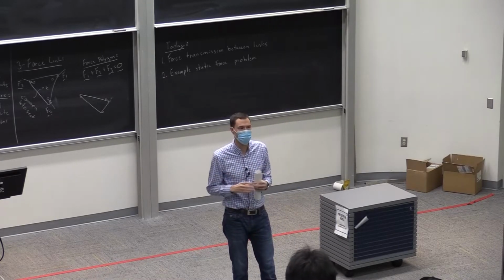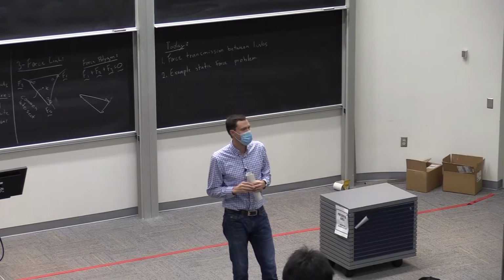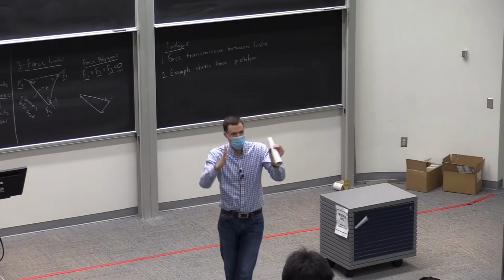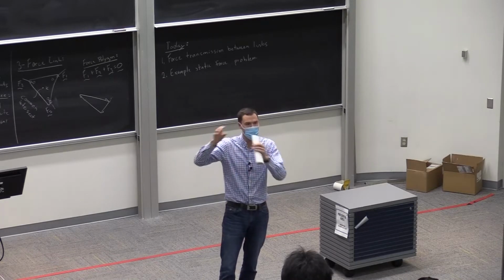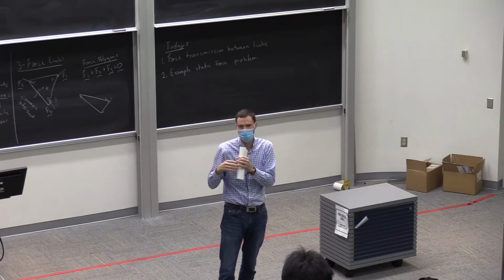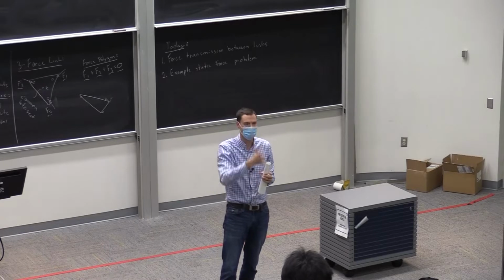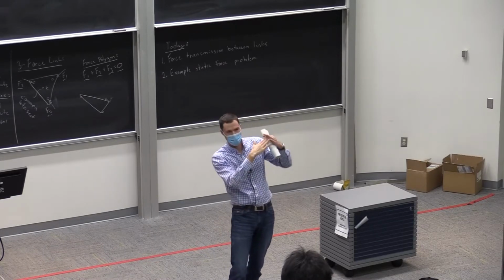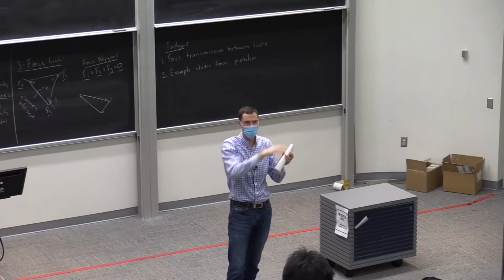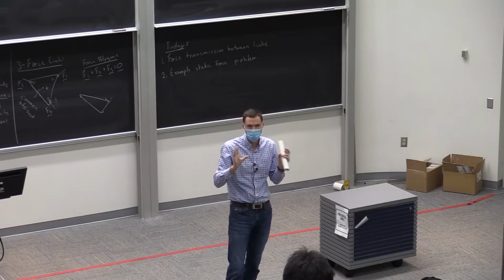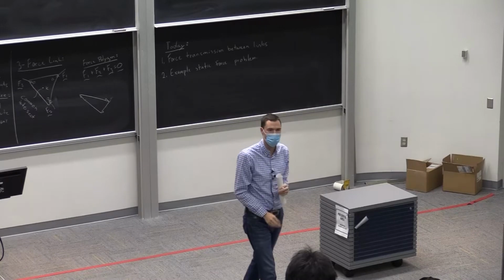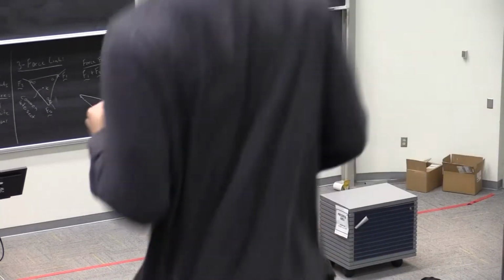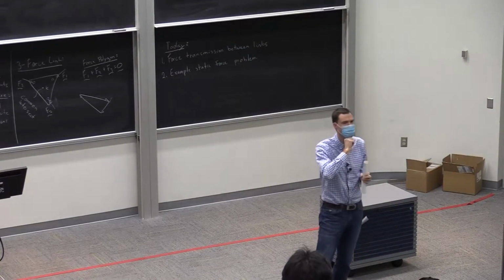To solve that one, you have to sit down and sketch out a few tries. And that's how I solve them. I make 3 or 4 little sketches, just rough sketches, and make some guesses. When link 2 is perpendicular to the next one, when it's vertical or horizontal, you can come up with maybe 2 or 3 candidates and then try and figure out which one is the limit all the way to the left or right.